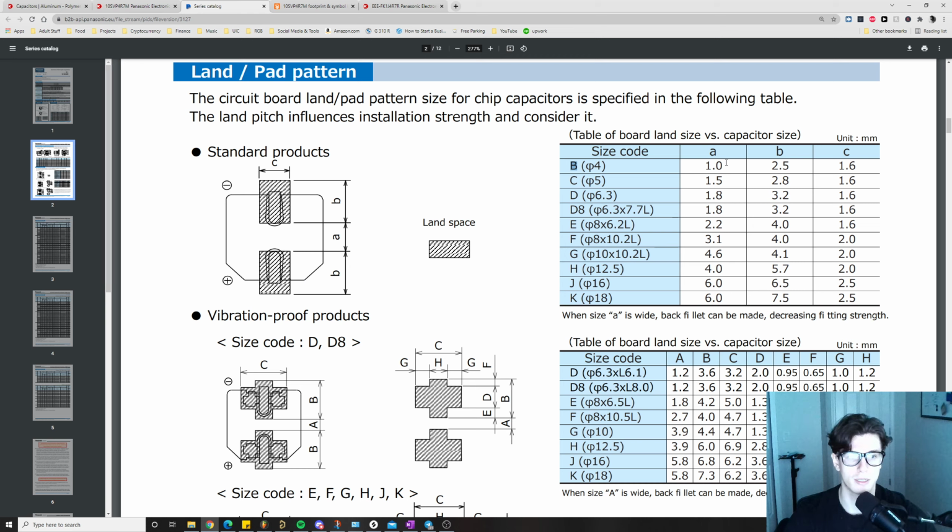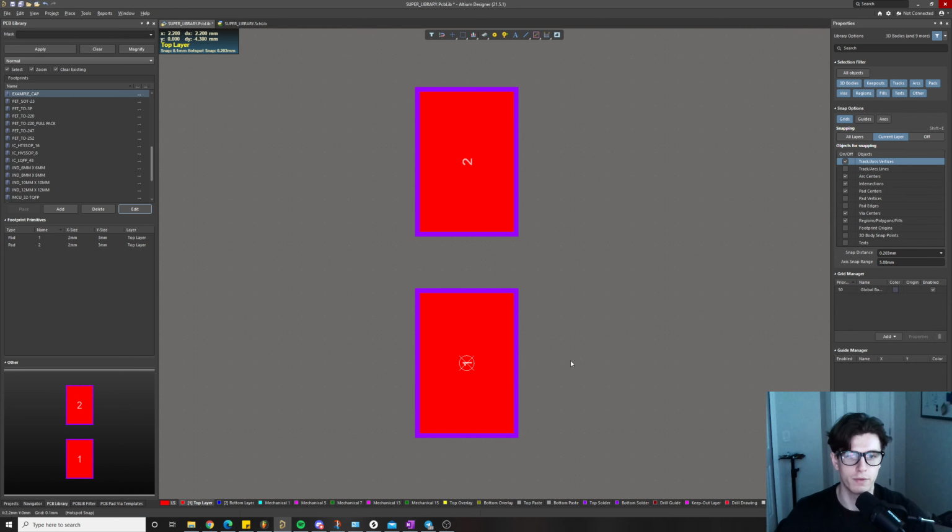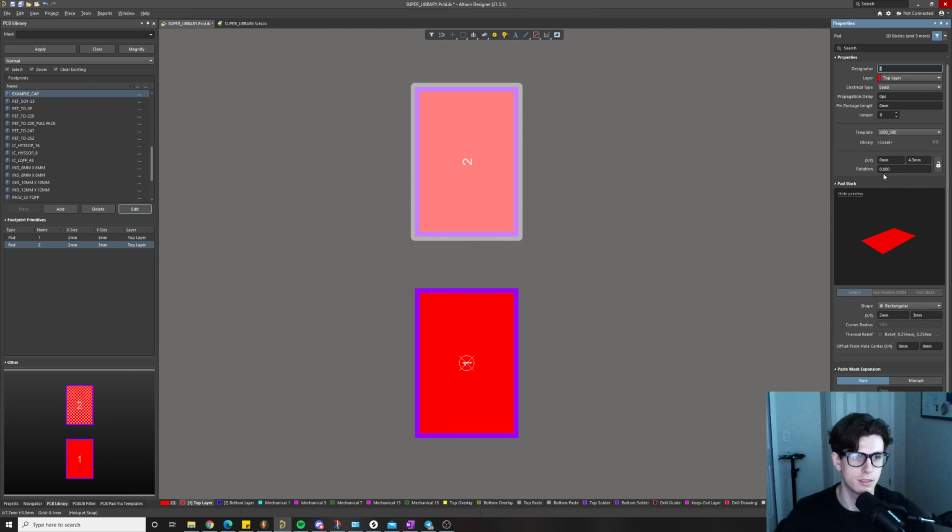B plus A is 3.5 millimeters. This one we want to put right on the money, because any wiggle room doesn't make sense, since this is a location and not a size. So we're going with 3.5 millimeters. This tells us the location: 0 millimeters in the X direction, because it's perfectly lined up with the origin.